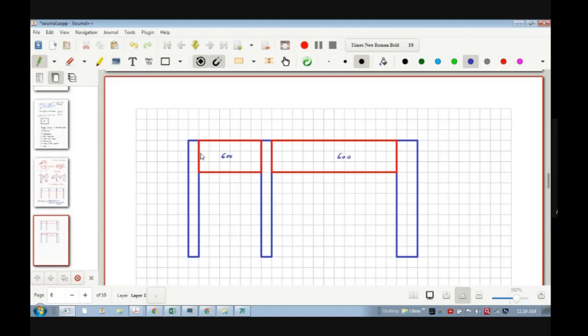So in both the cases, all of you know that there is a load over here. Load तो है ही, slab beam, wall वगैरह का. We have a bending moment diagram. Now let's say when this is the case, what is happening here? So due to the bigger span, the moment will be high here in this case. Let's say something like this. And as this is smaller span, the moment will be less. But as we are keeping the depth same, what will happen? This will have a uniform distribution. Let's say something like this.